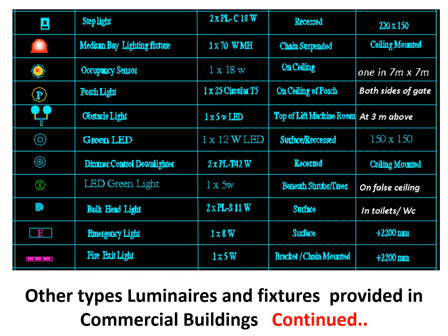Then an occupancy sensor is provided inside rooms having an area of more than 30 square meters as per energy efficiency rules. This is provided in the porch.